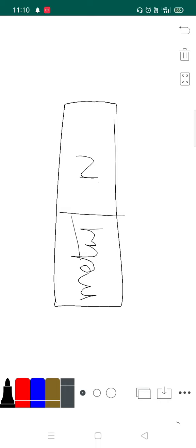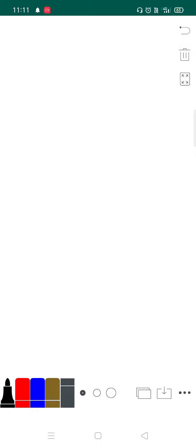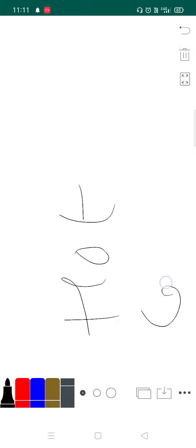So here electrons are injecting into the metal. The electrons in the N-type material have high energy compared to the electrons in the metal, so the charge carriers in the N-type material are known as hot carriers. The electrons in the Schottky diode are hot electrons. Once electrons in the N-type material enter the metal, they still remain majority carriers. The Schottky diode is unique in the sense that the flow of current is due to majority carriers.